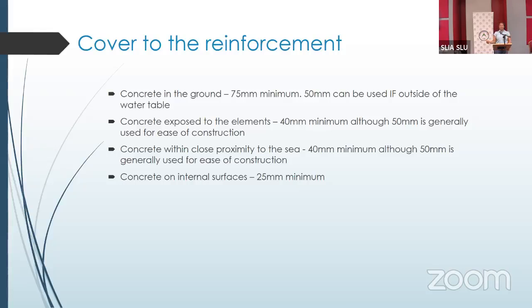and especially if we are within close proximity to the sea where we get sea blast, that salt in the water can also compromise the reinforcement alongside the water. So we generally use a minimum of 40 millimeters, although for constructability's sake, we tend to use 50 because 25 millimeters is equivalent to 1 inch. So it's a lot easier when we work with multiples of 25 instead of anything more or less or in between.